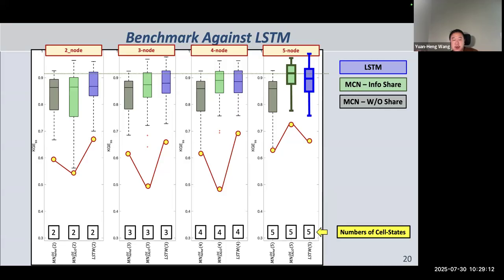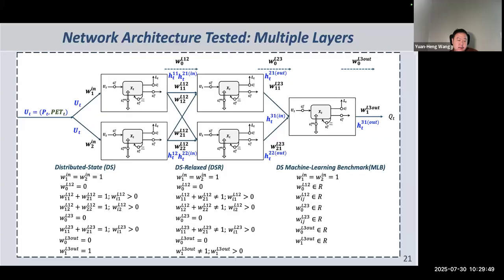But another issue is that the previous research trend on continental-scale LSTM uses mean square error or Nash-Sutcliffe efficiency type metrics, and these metrics are weighted differently based on the dryness and wetness at each location. But here I'm using the KGE as my objective function. So I think in the future, how to properly account for wetness and dryness in the KGE for future continental LSTM benchmarks is something we have to think about a little bit more.